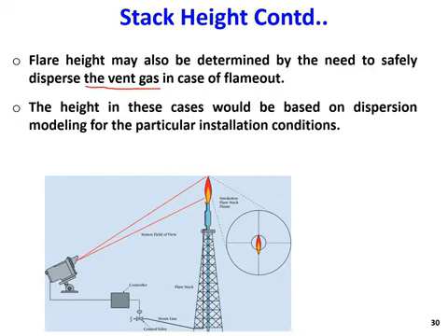We are not burning, we are just sending the gas to the flare. So it's sometimes very toxic, very dangerous. So we have to consider the amount of the gas that is going to be dispersed. And if we have more dangerous gas that has a higher flow rate, we have to increase the height of the flare. So how do we calculate that?